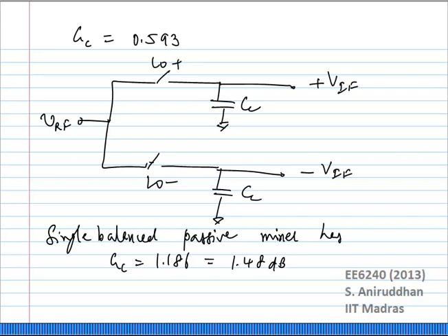Which portion? For the single balance, because you get twice. It's 2 by pi. The gain is still 2 by pi. We got a 4 by pi term when we did the analysis in class, but we had a 2 IRF at the input. Okay, we assume plus or minus IRF. So the gain for the double balance mixer is still 2 by pi in the active case.